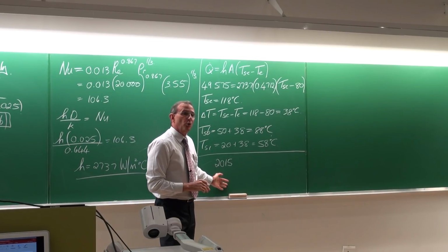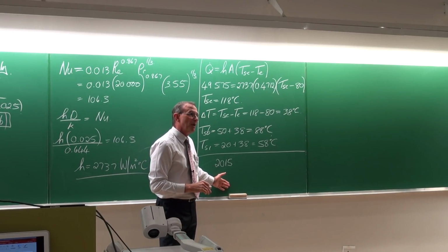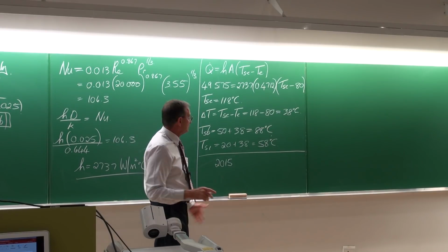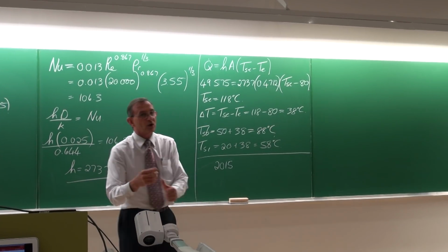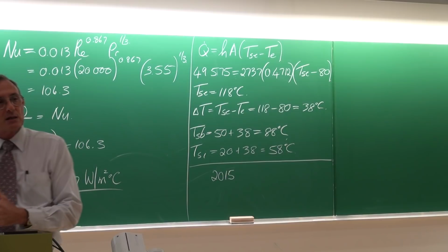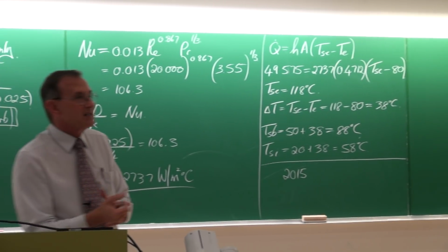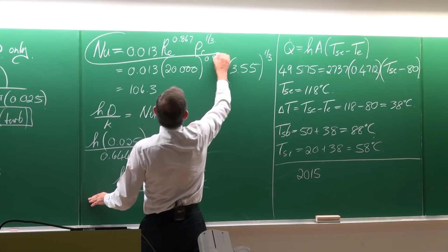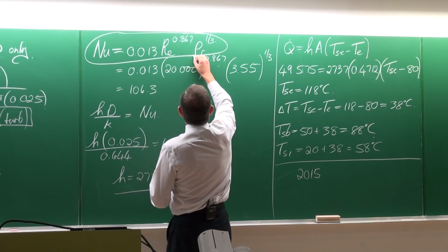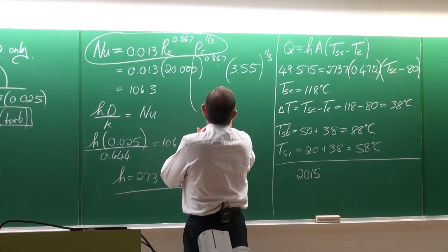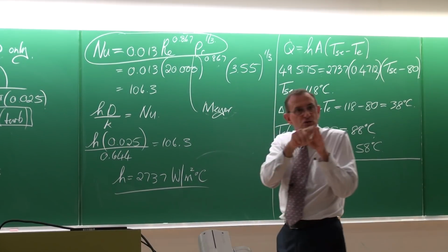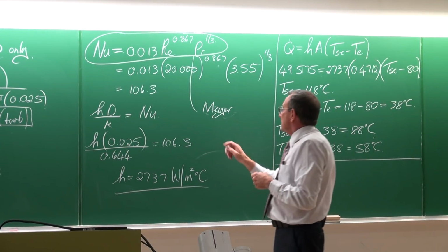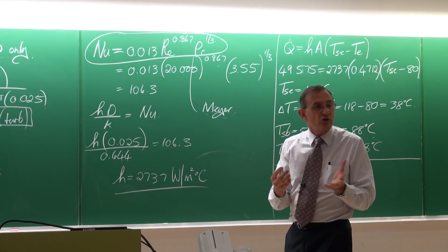However, the very important thing that you need to remember now is when the flow is turbulent, where previously we worked with Sieder and Tate, Dittus and Boelter, the Gnielinski equation, etc., then you need to replace this with the Meyer et al. equation. Et al. just means that you're not going to name all the authors because there are more than 2.